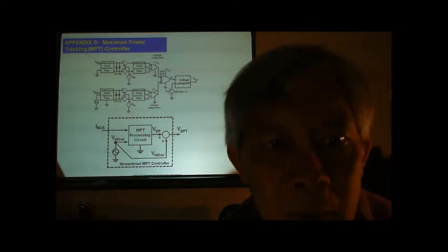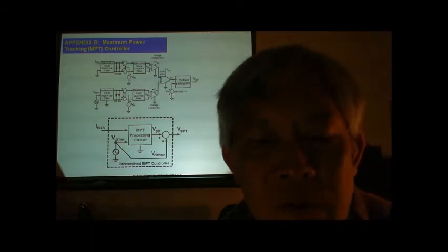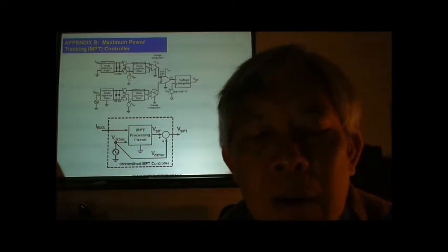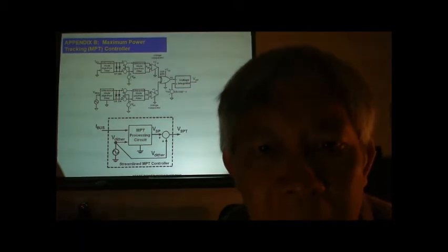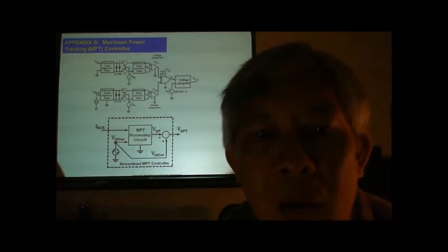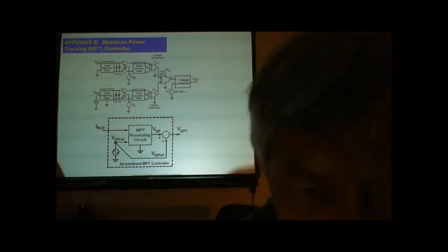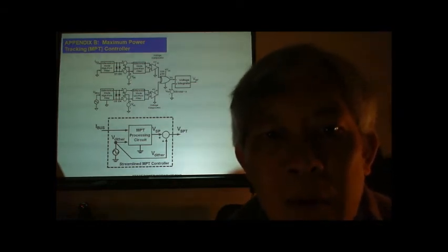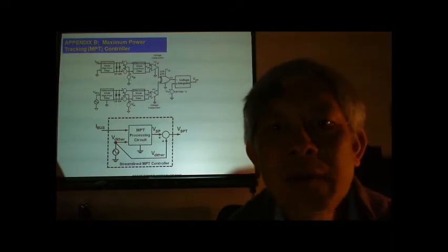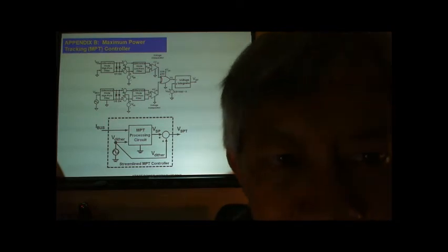When these two signals are in phase, which usually happens when the power operating point is on the left side of the peak power, they are in phase. And when the operating point is on the right side of the peak power point, these two signals are out of phase. And when these two signals correspond to the peak power point, they have an equivalent phase shift of about 90 degrees.